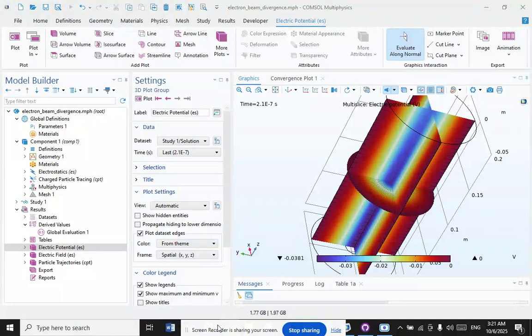Furthermore, it is shown that decreasing the beam divergence leads to a higher propensity to generate greater penetration keyholes. Also, during the transition from partial to full penetration through decreasing of the divergence, it is shown that some instabilities indeed form at intermediate beam divergences, while the compositional changes in the substrate due to preferential element evaporation during the electron beam welding process are not the primary focus of this simulation.